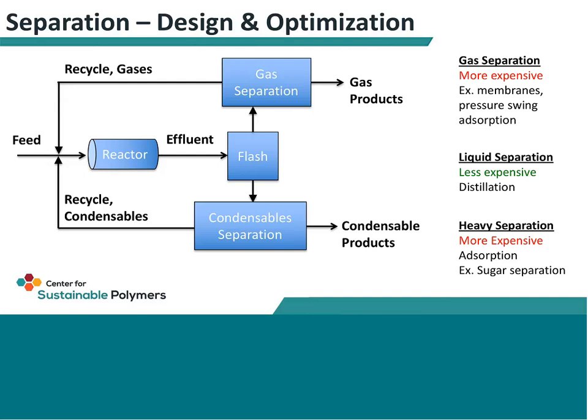This gets a lot more cost effective when we get something that's condensable. So if we have something coming out of the bottom of a flash tank as a condensable, and it's somewhere in about the naphtha to the diesel range, or a little above or a little below, we can condense it, in which case we can do distillation, which is actually much more cost effective.